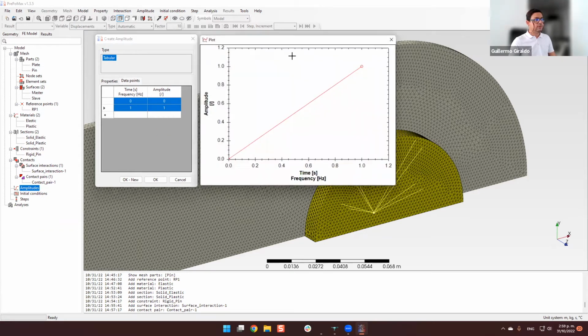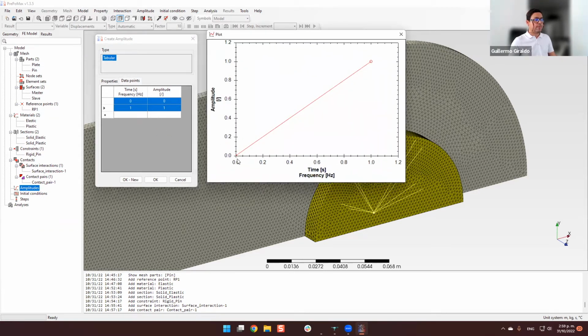So if I plot this, you can see what we'll do is just ramp up the load. I will start my load from a factor of 0, and at time 1, I will get a factor of 1, or 100% of the full load. And then I can control this by subdividing this time portion by a time variable, say in 10, in 20, in 50, in 100 points.